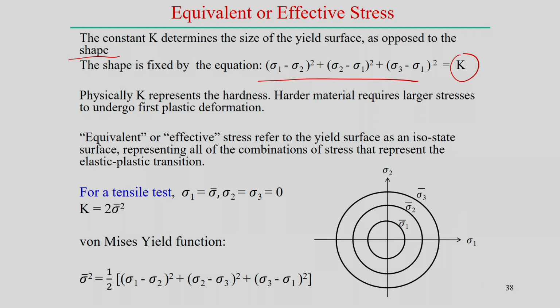Now, if there is a change of the value, for example, from the uniaxial tensile testing we can find out the sigma 1 value, which is the yield point, the first yield point, just the elastic to plastic zone. Then with the strain hardening effect it changes. So, if we incorporate the strain hardening effect, the yield surface is about something like that: it is the first yield point, then this is the next yield point. Next yield point means it moves from here to here because of the strain hardening effect of a particular material. Similarly, it changes from here to here, from here to here.